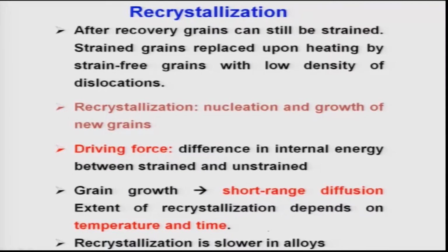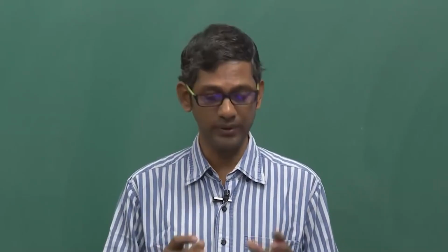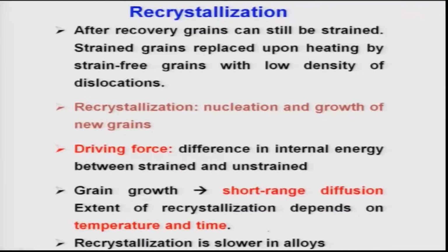Now recrystallization is basically nothing but nucleation and growth of new strain-free grains. Remember, new strain-free grains. It is not only new grains, the grains which will be forming, or crystallizing, or growing again, are strain-free. What is the driving force for that? Obviously, the driving force is the strain and stored energy in the material. The difference in the internal energy of the strained and the unstrained, that is the driving force. And grain growth, as I told you, is driven by the grain boundary energy. So this depends on both temperature and time.